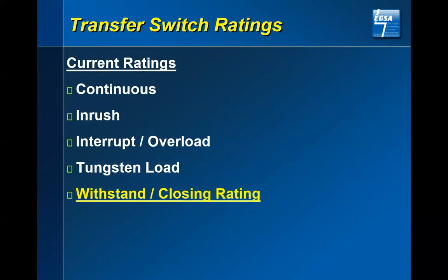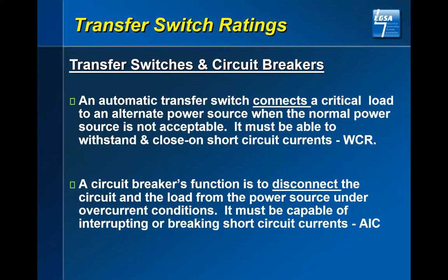Back to the thing that you're going to get tired of hearing me speak about, the withstand and close on rating. An automatic transfer switch connects a critical load to an alternate source. It must be able to withstand a close on. Let's talk about those 2 terms for a minute. A circuit breaker has an AIC rating, an amps interrupting, okay? Its whole purpose is to open. That's it.